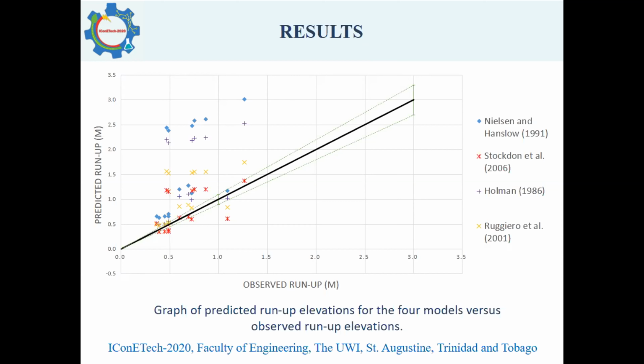of wave runoff. For instance, if we take a look at swash infiltration, these models, unlike many other models, assume an impermeable beach, which is not quite the case. So if we were to say that as the swash lens travels further up the beach, covering a larger surface area, not taking into account permeability, we would then expect, theoretically, a greater overprediction of wave runoff. Other morphodynamic parameters, such as friction and wind, may also account, well, the omission of these parameters may also account for the overprediction of wave runoff.